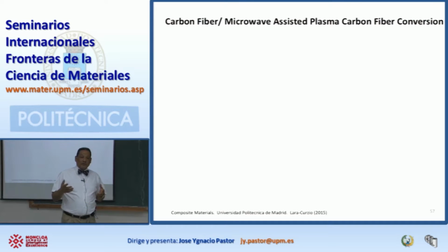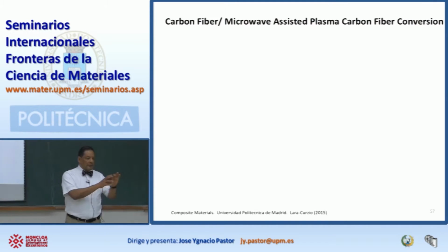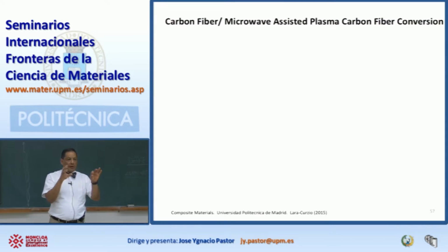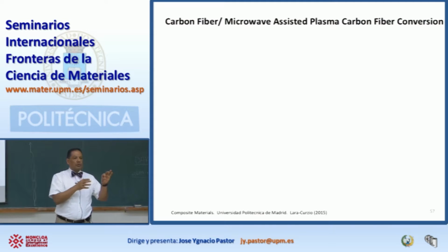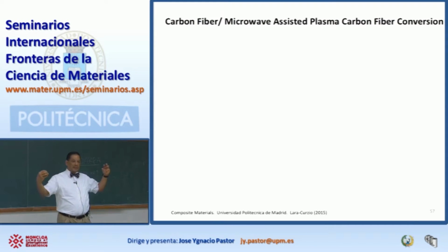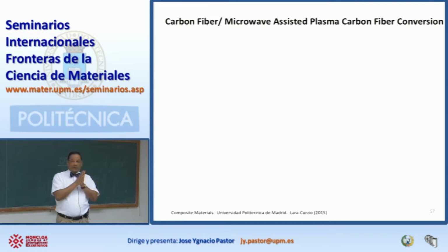These things are related. If you think about it, a carbon fiber may have 5 microns in diameter, but a lot of these fibers have an onion skin type of structure where you have layers. And what you have in these carbon fibers are layers of graphene, one on top of each other. When you pull the fiber, it's very stiff, very strong, because you are actually pulling against these carbon-to-carbon bonds. The fibers may be put in shear. Have you seen these telescopic lenses, where you have a cylinder and then you can extrude the cylinder? That's what happens with these carbon fibers. That property in shear is very low because it's just constrained by van der Waals forces.